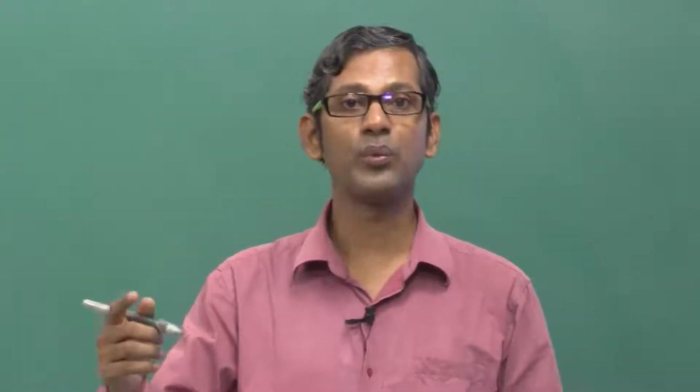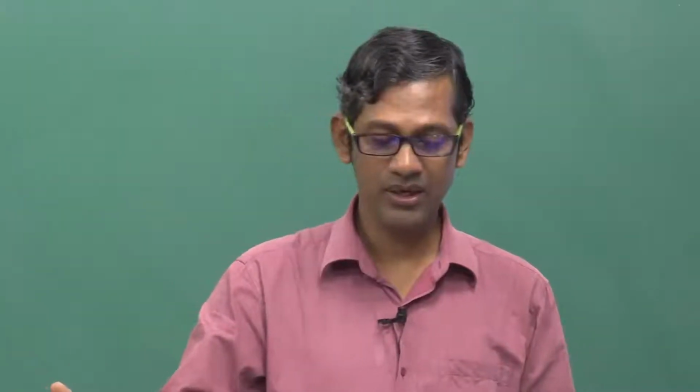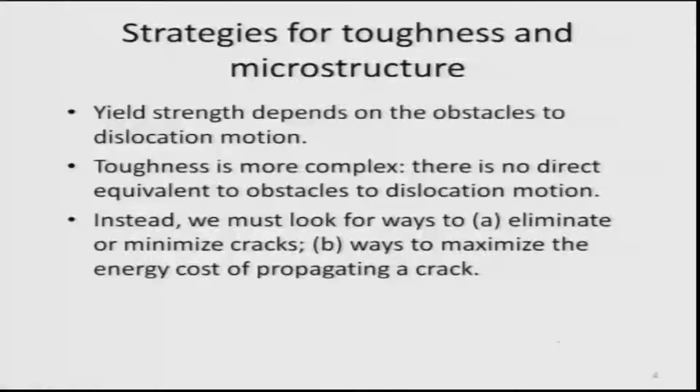So, therefore, if you want to increase the toughness, we must look for ways and means to eliminate or minimize the cracks. In fact, elimination of cracks completely is an ideal situation, impossible in the world. What we can do is minimize the cracks, or the other way is to find ways and means to maximize the energy cost for propagation of the cracks. As I said, it is very difficult to eliminate cracks.